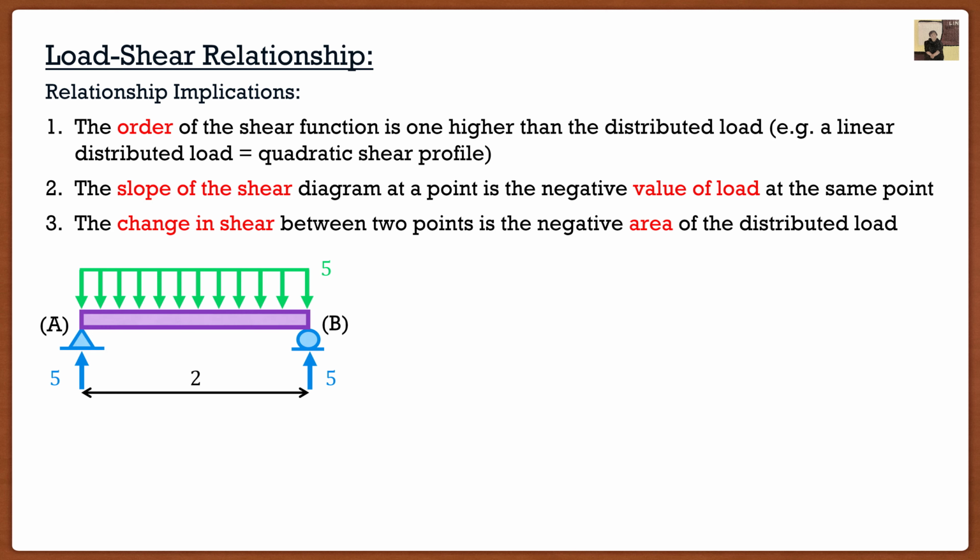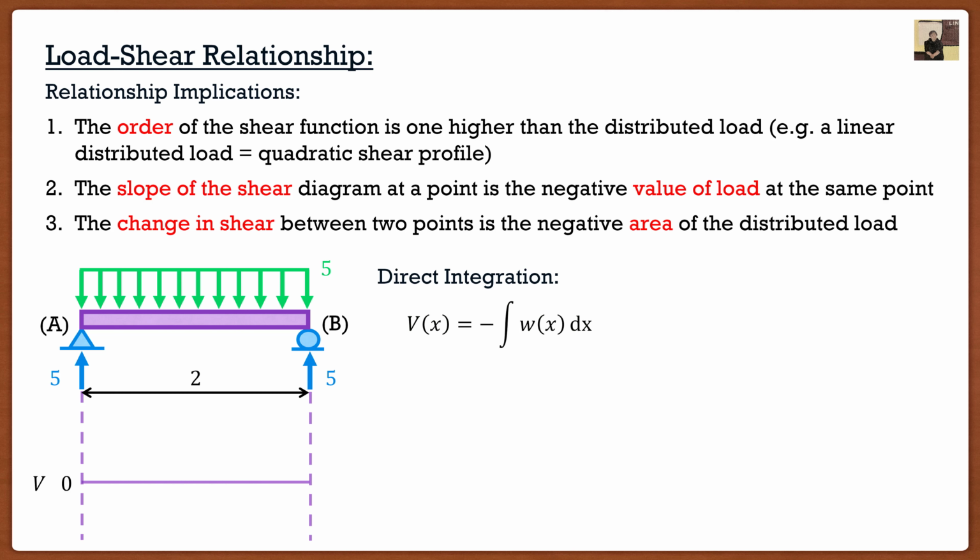Now let's show this in action so you guys can kind of see what exactly is going on. So let's say I have my beam here, and this is the beam that we solved for in the previous video where we did the cutting method. So let's see how we can use relationships to make our lives easier. So of course we have our beam, and we're interested in our shear force diagram. So again, the first method, we can directly integrate it. We know that our shear force function is the negative of the integral of our distributed load.